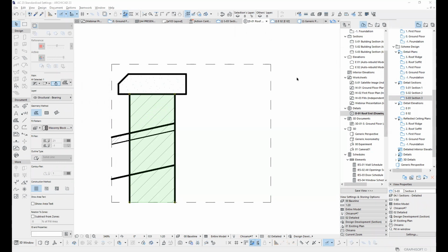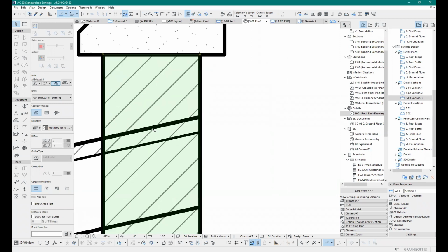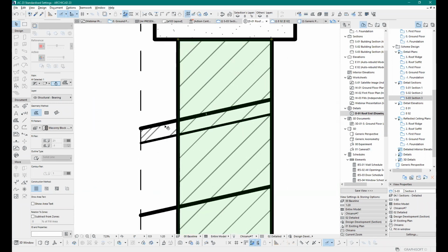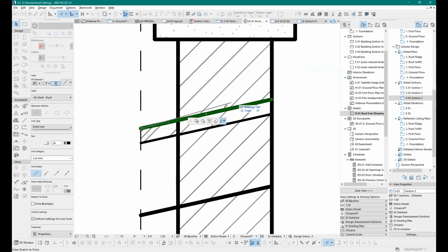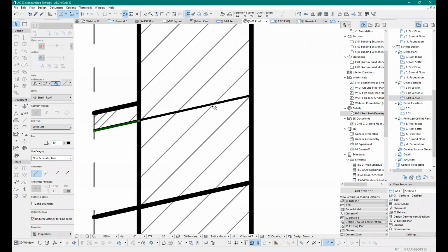If you suspend your groups, you can select each separately. And the boundary lines, or the cut lines on your models, become purely lines. So I can extend that, bring that to here, select this as well, bring that there. It's created two lines. So that as well.